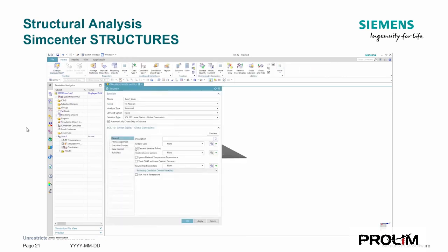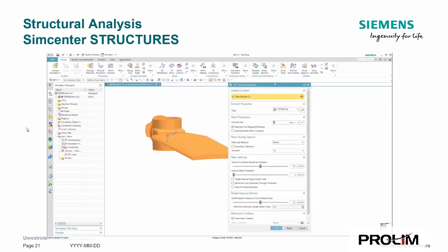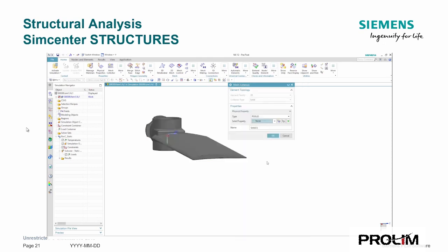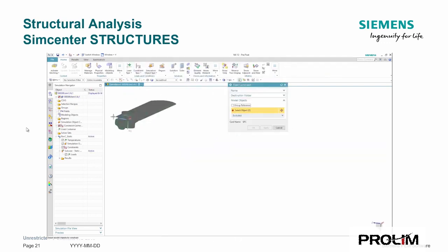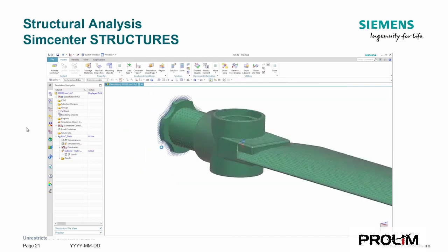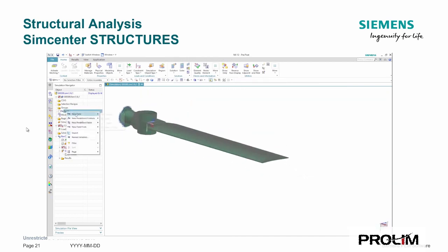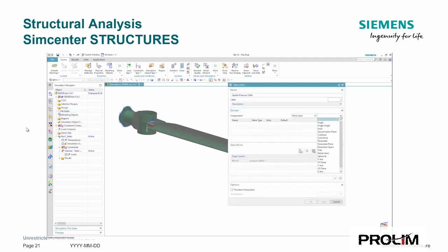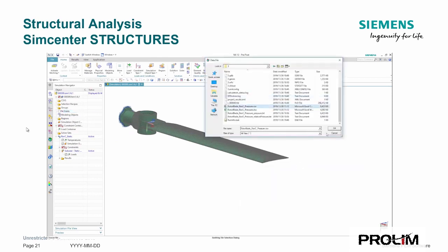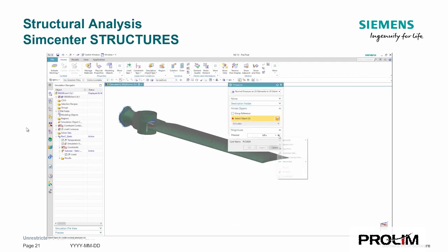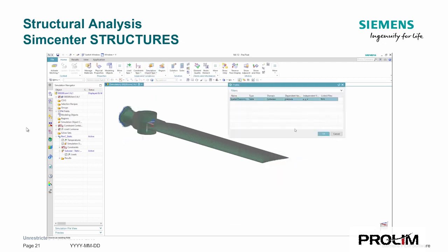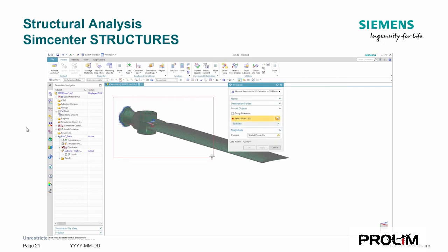And here you can just see a quick run through of the setup of the finite element analysis, where you will see the file being imported from the pressure distribution and mapped across to the finite element model as a new field, picking up the file that was exported from FlowEFD and applying that as a pressure distribution field.